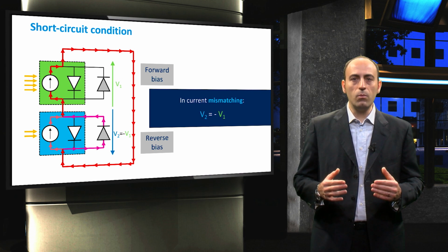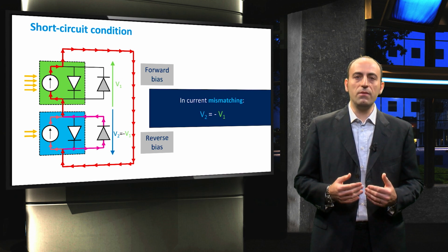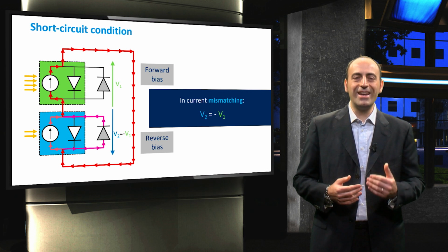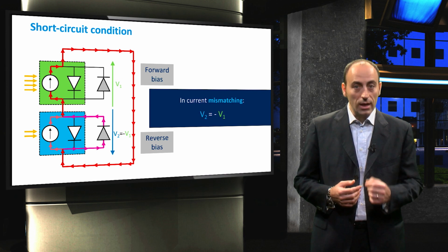This means that when we have two cells in series that are short-circuited, then the cell receiving lower irradiance would see a negative bias, which would activate the bypass diode that is mounted counterpolarized. So all the excess current that would eventually flow inside the cell actually flows within the bypass diode, preventing the cell from having a large amount of power being dissipated in it.